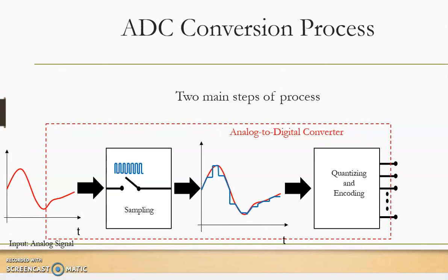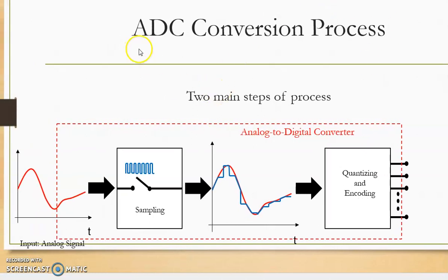Now this is one diagrammatic representation of how the signals from the ADC, that is the A to D converter, are handled. So we receive the analog signal, right? Then the sampler or sampling element is placed, and as you can see, these blue lines have been converted into discrete or digital signals, and after the coding the computer can accept the data. So that's how analog to digital conversion takes place, mainly by using these steps. So the sampler and the coding mechanism are used for the computer to accept the data.